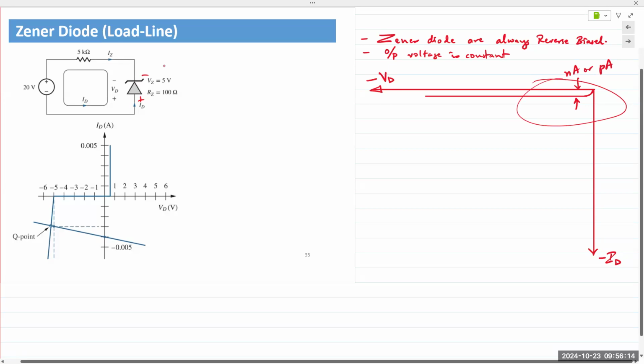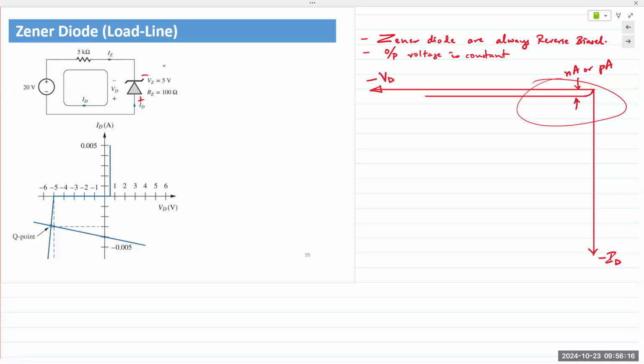Okay, the diode characteristic passes through the origin. So in the forward bias and the reverse bias, in the reverse bias specifically, you have this current that's flowing, which is of course the reverse saturation current. In real life, again, it's in the nanoamps range. It's almost a near flat line on the negative x-axis.